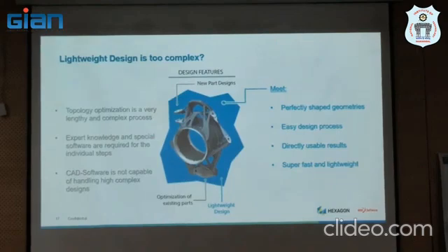As I said, when we jump into it, we have to start with multi-body dynamics to understand what the vehicle is designed for, and what weight is coming to each wheel joint. The wheel hub at the same time is critical. It is connected to the suspension, it is connected to the brake pad, and it is connected to the wheel, and the whole vehicle load is coming to this component. If it fails, the vehicle will stop. So we have to take both the loading condition and DFAM into account, and we can do further optimization.